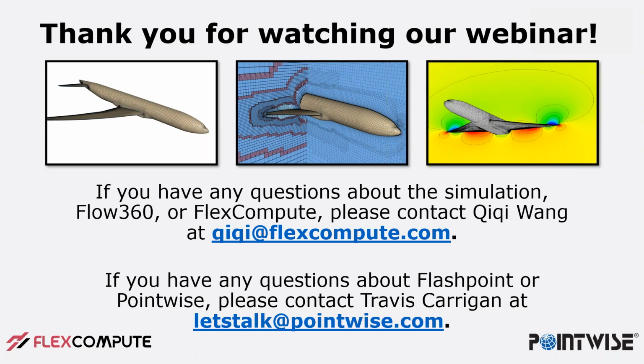And the mesh that I get is often better than the mesh I could have created by hand, because there's a lot of things going on behind the scenes that I would have to sit down and pull up a calculator and figure out how to set distributions, how to set spacings, and all of these types of things, right? So it's making a lot of those decisions for us behind the scenes. So it's much quicker than doing it by hand. And if I did want to modify anything, I now have a foundation created automatically that I can then go and modify as much as I want. So I hope that answers your question.